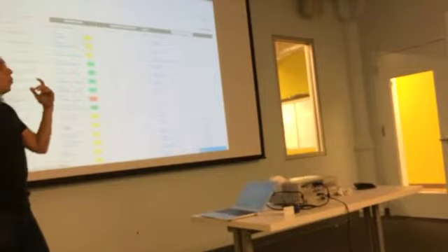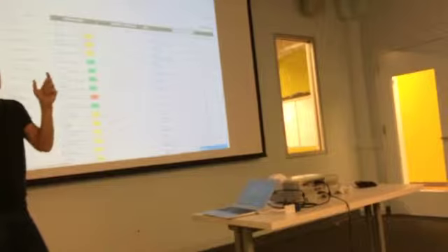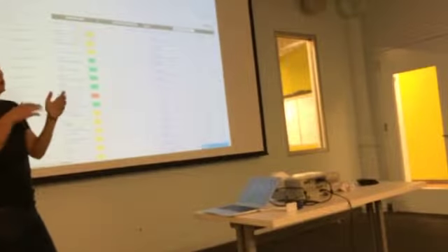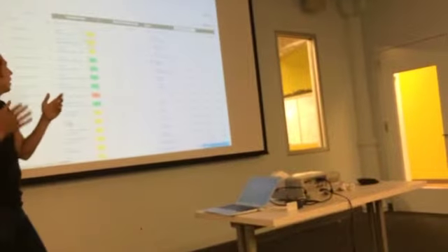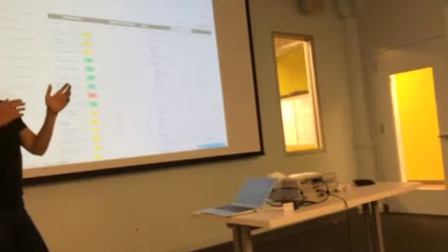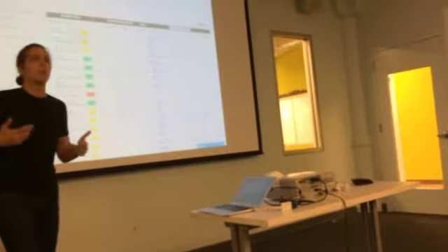The next column, selected distributors. This you can add the pricing and availability numbers from individual distributors. And so right now it's loaded up with DigiKey, Mouser, and Newark. You could add Farnell in there. You could add Avnet Express in there, or you could remove Mouser, and you can customize it to the distributors that you're comfortable with working with.